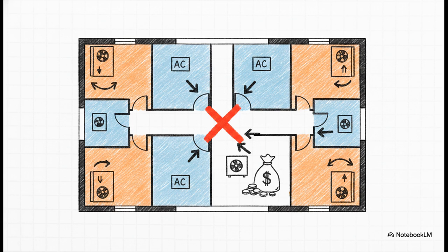This is exactly why true professional designs use a hybrid approach. They throw simple, cooling-only systems on the inside and put those versatile heat pumps on the exterior perimeter. You have to design for the space, not the building.